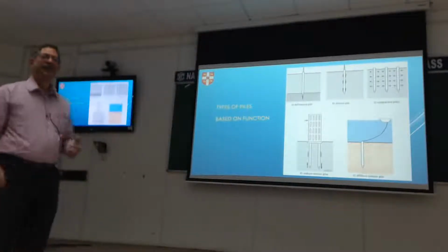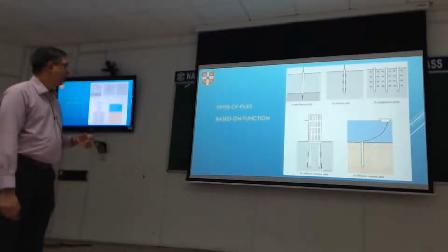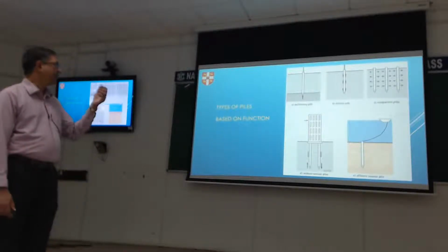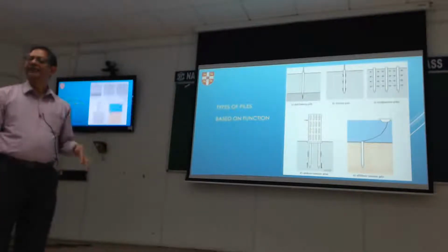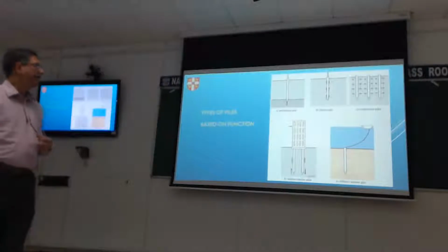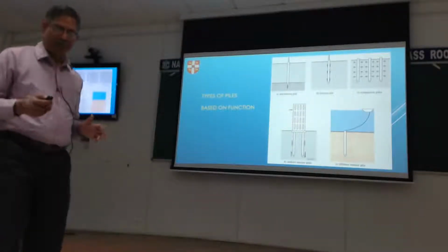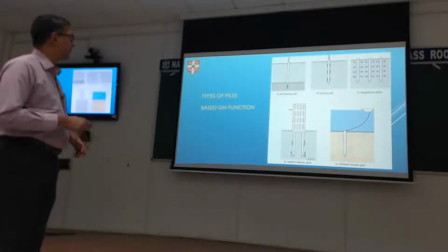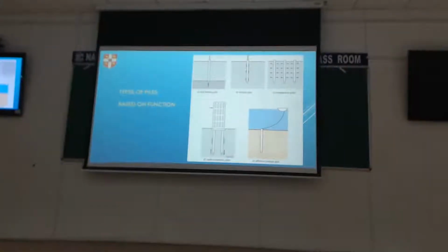You should have asked me what type of pile you are talking about, because there are many different piles. You can have purely end-bearing piles. Say you have very soft clay and then sand below. You basically design them as purely end-bearing. You can have the opposite case where you have only friction, because there is no stiff layer or bedrock.